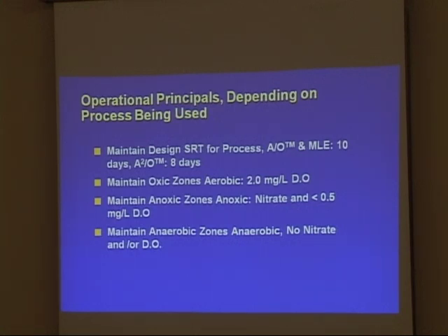those organisms. But if you have a power outage, something like that, or a blower goes down for a while, you have no oxygen going in there for a while, it'll bounce back pretty quick. I wouldn't want to tempt fate, though. We were very fortunate when we were doing that one blower test, we ended up getting through it that day just because you had a precipitation event and your oxygen demand wasn't very high to begin with. This is something to kind of know.